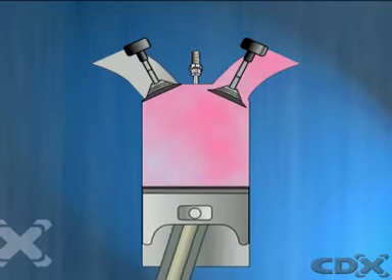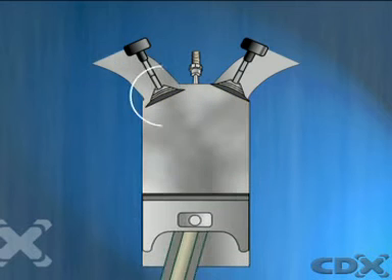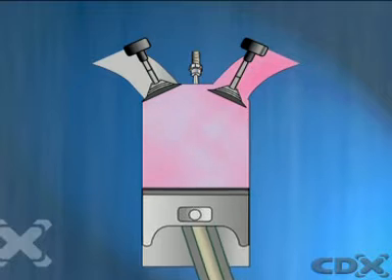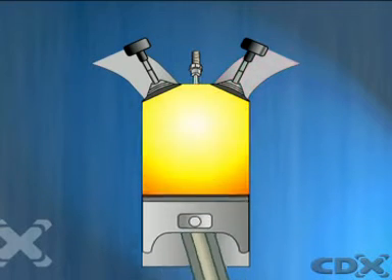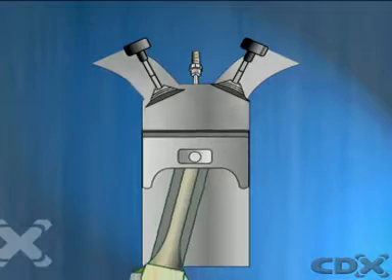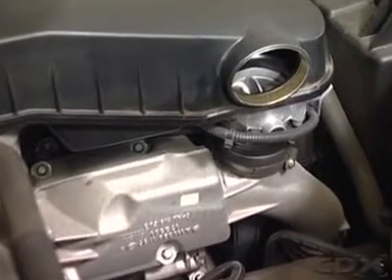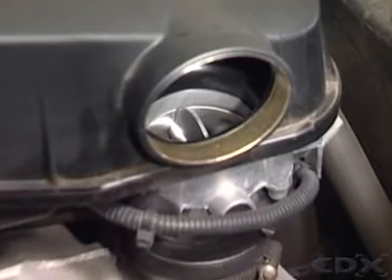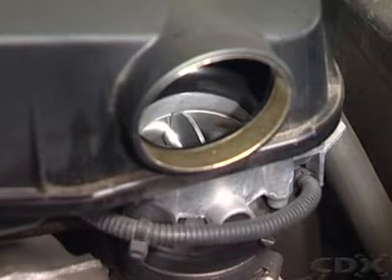The effective expansion stroke is lengthened by delaying the opening of the exhaust valve, so all the pressure created by the expansion of the combustion gases can act on the piston until they're completely dissipated, applying pressure to the crankshaft for a longer period and increasing efficiency. Both engines use a large throttle opening but induce a small amount of air. This results in lower manifold vacuum, reduced pumping losses, and increased efficiency.